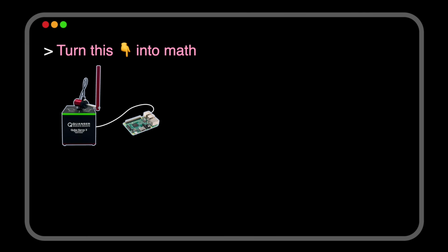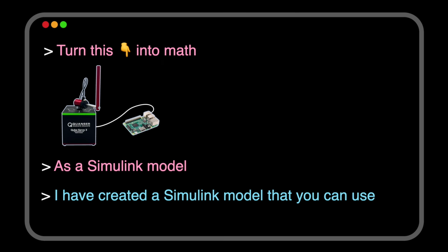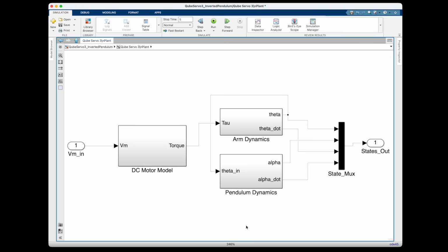We're using model-based design for controller development, simulation, and verification, which means that we need a model of the system. Now, instead of just letting the agent create a model however it wants, again, we want to think about what it is creating so that we can understand it and check it and potentially reuse existing models if available. So for this project, we could ask the agent to produce a Simulink model. And this is great because it addresses both of those issues.